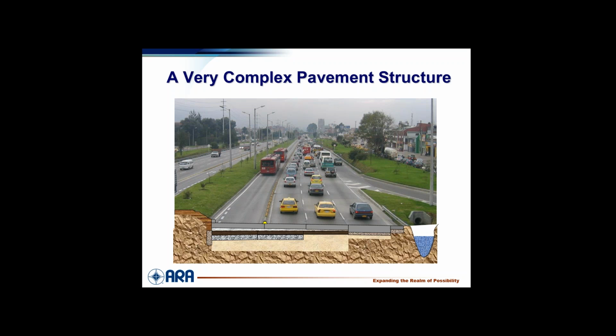It was an old concrete pavement that had been overlaid and extended and widened. And now for this design, they actually put in what really was flowable fill, sand and cement. Maybe a little fly ash, not much. But this ranged from 4 inches to 10 or 15 inches or more. And it kind of evened this up, rather than put hot mix, which they very well should have done, because this starts eroding, as you might imagine.